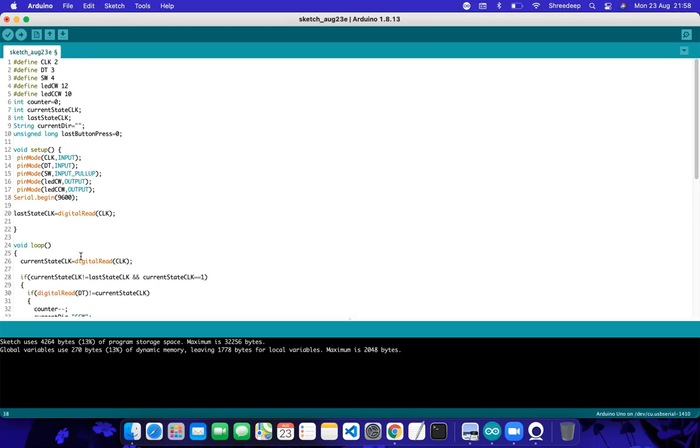That's a program which is separate from the software, and you don't need to call the program. In the previous case, what I've shown you, the blink function needs to be called from the main program, that is from the main void loop, right? Let's say you have written the blink function but forgot to declare it within the void loop. Then there's no way it will be called, and it will not perform your task.